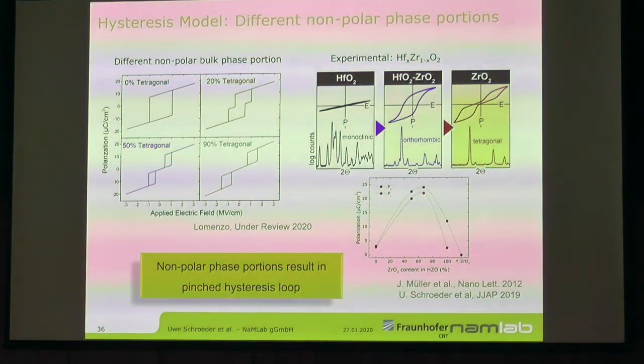We think the pure zirconium oxide still has, and that's also what we find in XRD measurements, probably something like 20% of the orthorhombic phase in the material. And you would have to add, and that's what you find already in literature, some yttrium to the zirconium oxide, like yttrium stabilized zirconium oxide, to really get the material tetragonal and not ferroelectric anymore for these thin films.